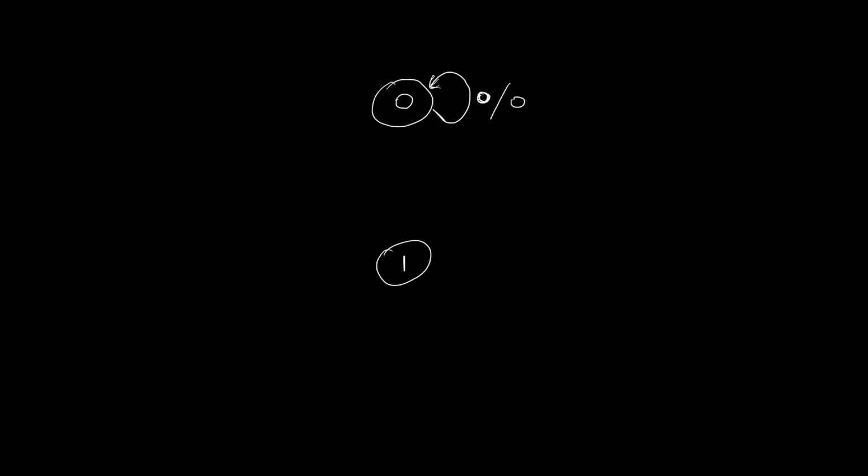On the other hand, if the input was a 0 and is now a 1, and if it stays a 1 at the rising edge of the clock, then I transition to this state to signify that my previous input was a 1. So this is if the input is a 1, and if the previous input was a 0 and the current input is a 1, that's a transition, so my output is a 1 here.